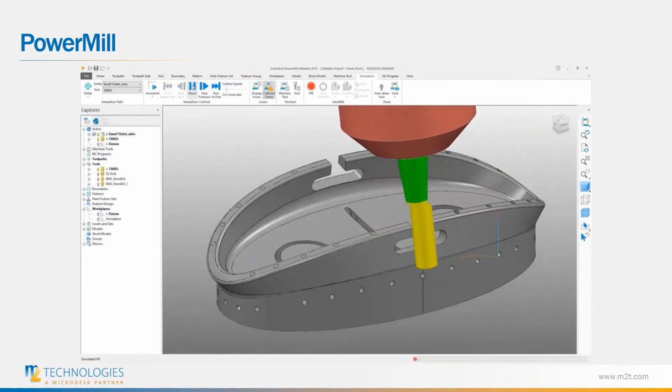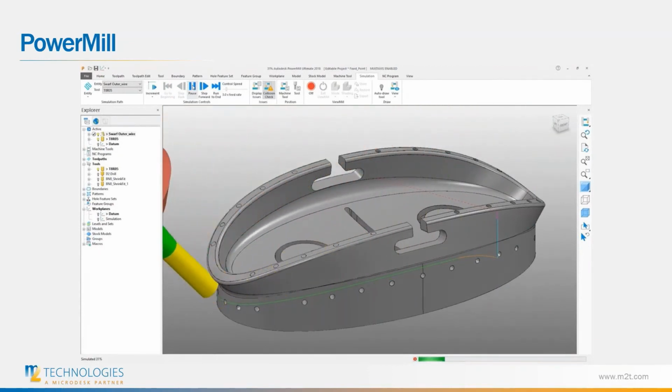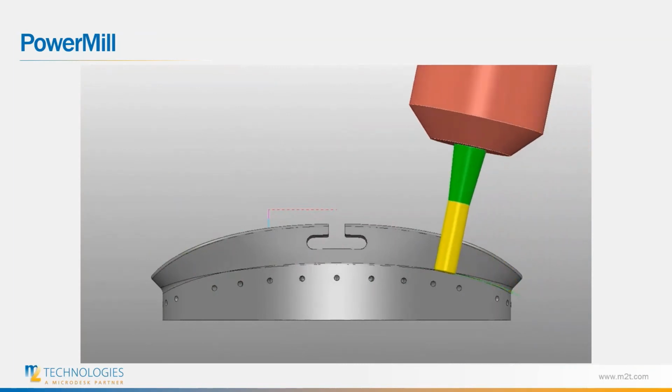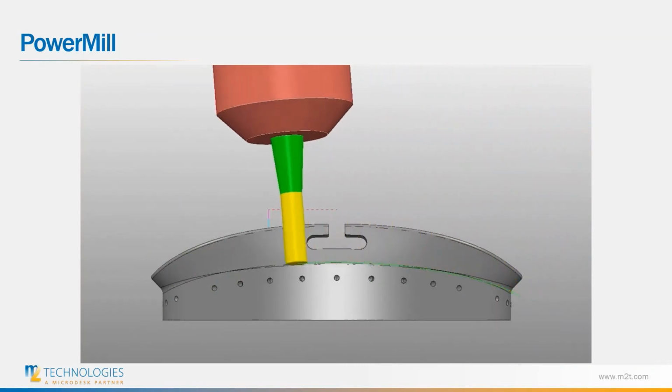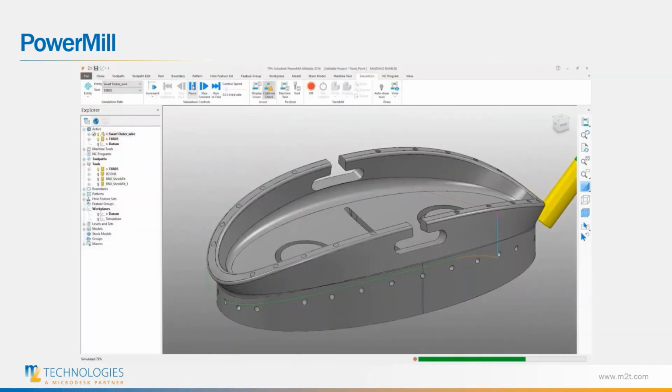Automatic tool axis control is ideally suited for use with toolpaths such as swirl finishing, where the side of the tool is aligned with the feature being machined. This style of feature machining is used to cut pocket sidewalls and other ruled features with ease.